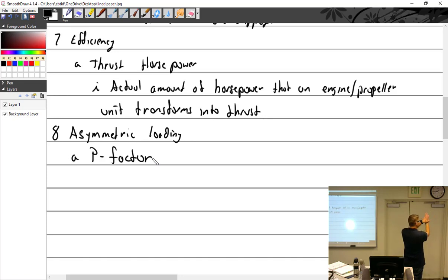When you raise the tail up, it's like you pushed on the prop right here to get it up. You're pushing the prop here to bring the tail up, but the prop feels it going 90 degrees that way. It's like I grabbed this prop tip and just pulled really hard this way. That's any tail-wheeled aircraft. When you bring the tail up, that's why you have to have a tail-wheel endorsement, because you can't just go out and fly a tail-wheeled airplane without being aware of this stuff.